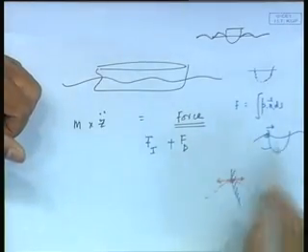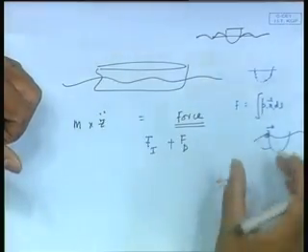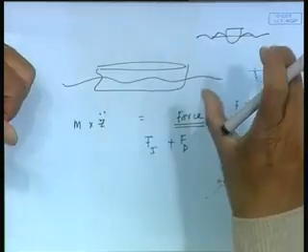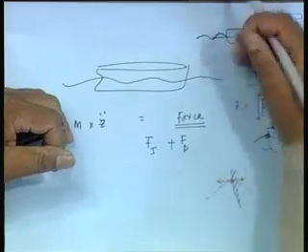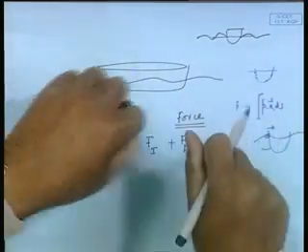Now here, what happened? Net effect is that the body is moving, but if the body did move, it would have created one more system of waves around it, because any free surface you oscillate will create one more system of waves. Now if it created this system of waves, again that will create a pressure field. In fact, it is very obvious to see that the energy that you input creates the waves, and that energy gets dissipated in the form of waves.